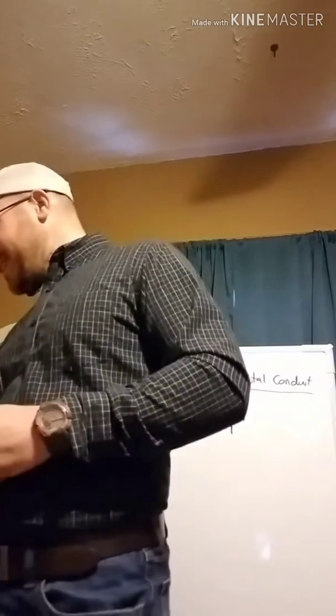342.22, number of conductors. That's our conductor fill, Chapter 9 tables, which we went over. And if people need some more help with that, I can do a video on how to calculate conductor fill for conduit at another time.